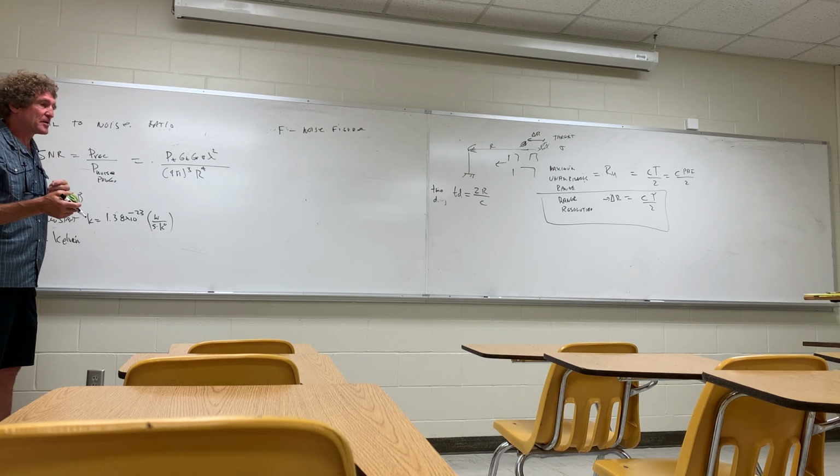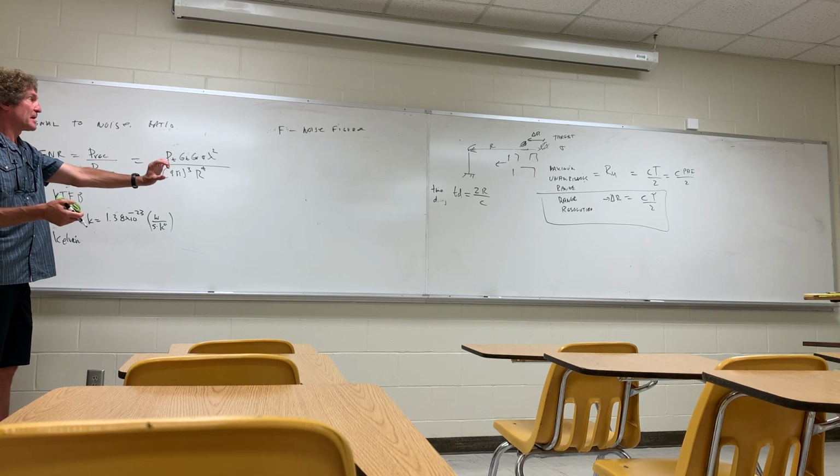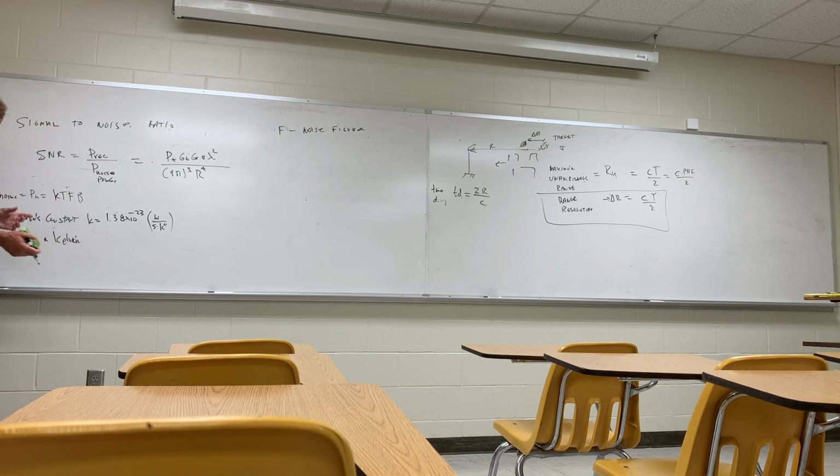Without any signal being transmitted, we can measure the amount of apparent noise that is developed, and we know that this should be the noise power. Do y'all follow me on this? So this noise figure we adjust so that the noise power equals this equation. This is how they do it. I'm not kidding about this. So this is the equation they're trying to balance.